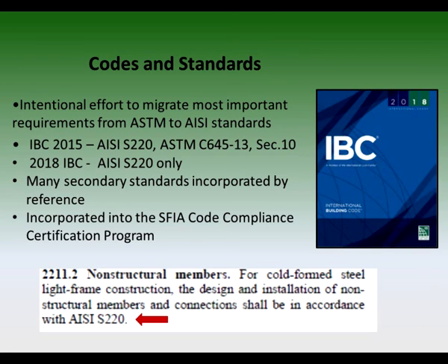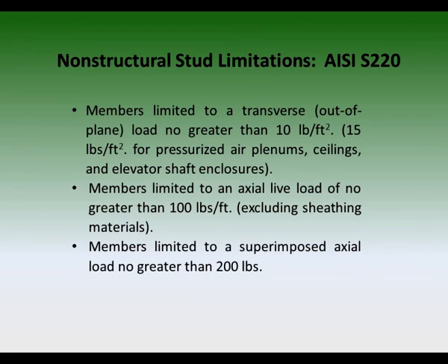Fortunately, SFIA has taken some of the mystery out of code compliance with its Code Compliance Certification program. This is especially helpful for specifiers, designers, and code officials for EQ studs. Before we touch on the SFIA program, a quick definition will help so you know what type of studs we're discussing when we use the term EQ. Actually, this definition applies to any non-structural application. We're basically talking about interior studs that have limited live loads. For example, a partition wall.